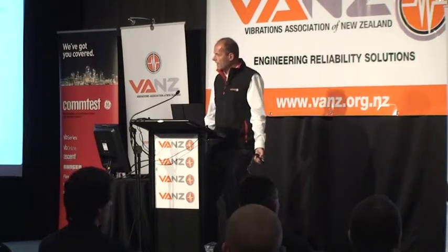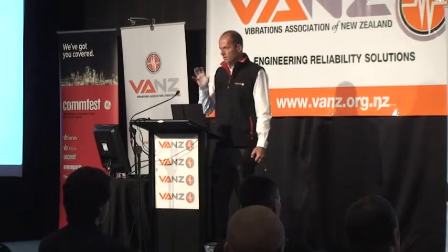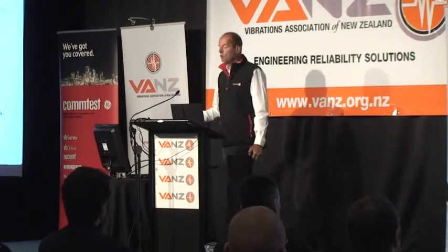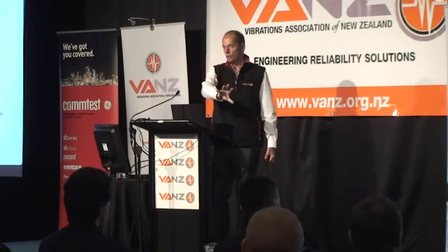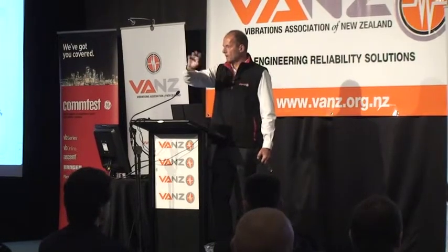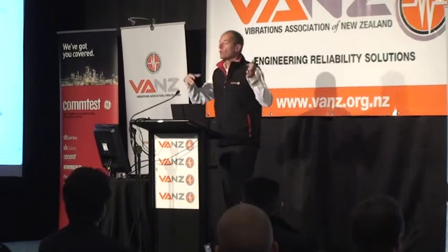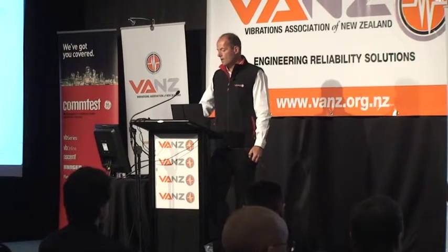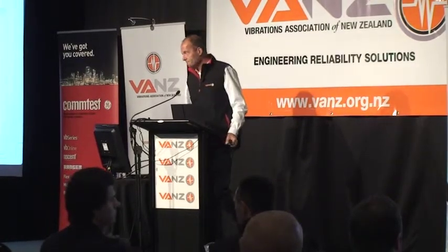So, we all know that breakdowns can be frustrating and costly and everything else. But fortunately, there is a solution. We can monitor the equipment to find these problems early, but what we really want to do is improve the condition. Use our monitoring techniques to look for the root causes, the unbalance, the misalignment, the contaminated lubricant, and deal with that. But step further out and make sure that those problems don't happen in the first place. And we can all be happy. Thank you. That's my presentation.